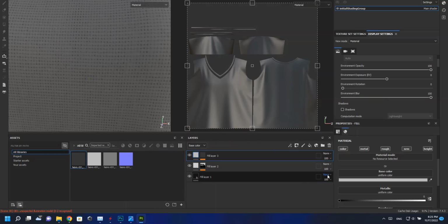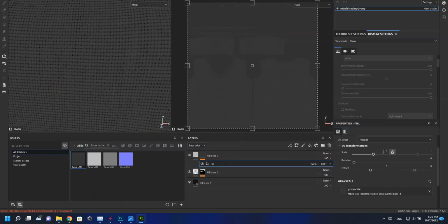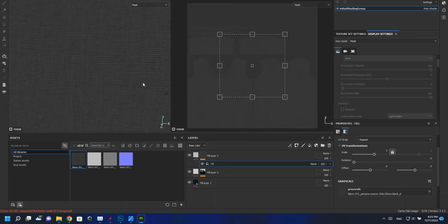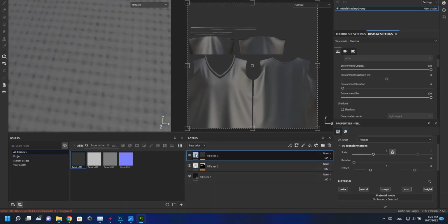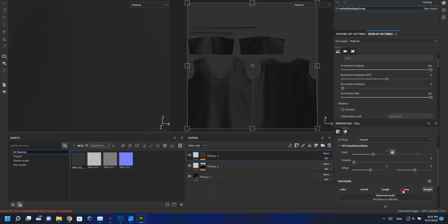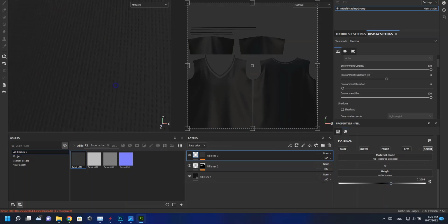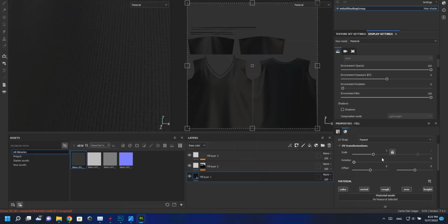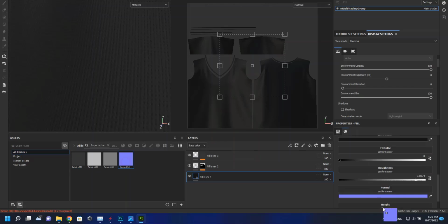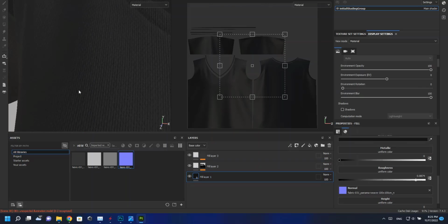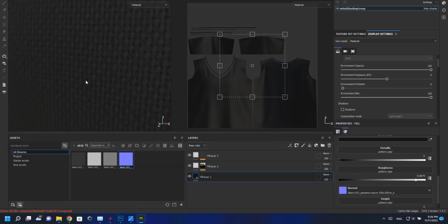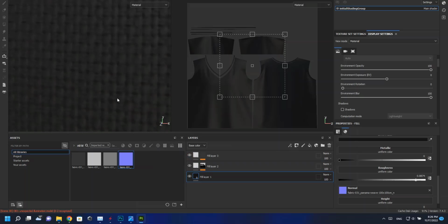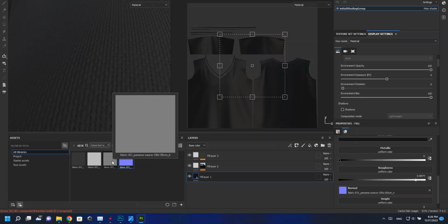we can achieve the desired material. To add clearer noises and irregularities in the material and add fine and messy details, it is better to use noise textures or grunge and adjust them manually. There is another type of this detail called a smart mask, which cleverly creates a series of details and irregularities based on bake maps. Using these items is very useful in some situations, but it is not good to overdo it. Using generators is also very useful.